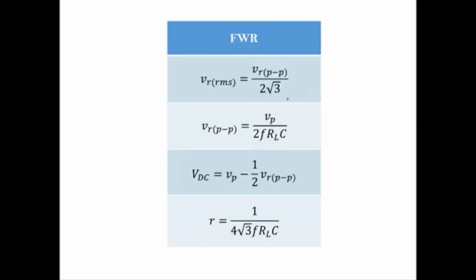This table summarizes the important equations for the waveform related to the filtering circuit. For the waveform after the filtering, the general pattern of how to draw the output is, let's say this is V and this is T. First, you need to have the full wave. You put a dash line as your guide line, for the full wave after the rectification.